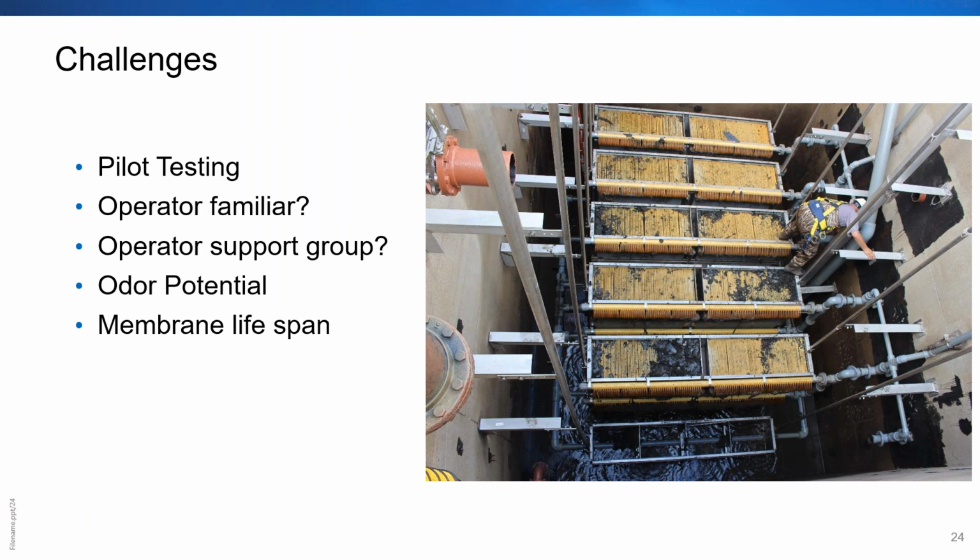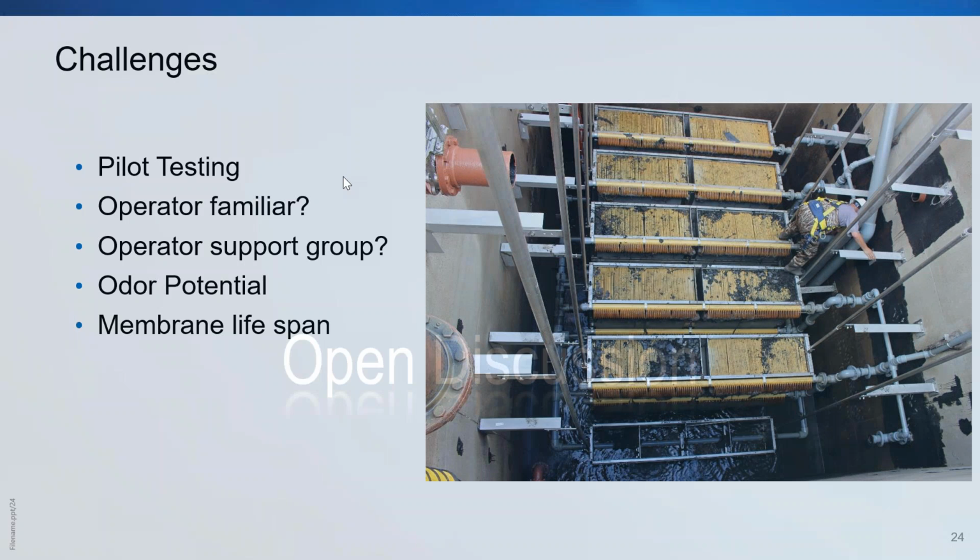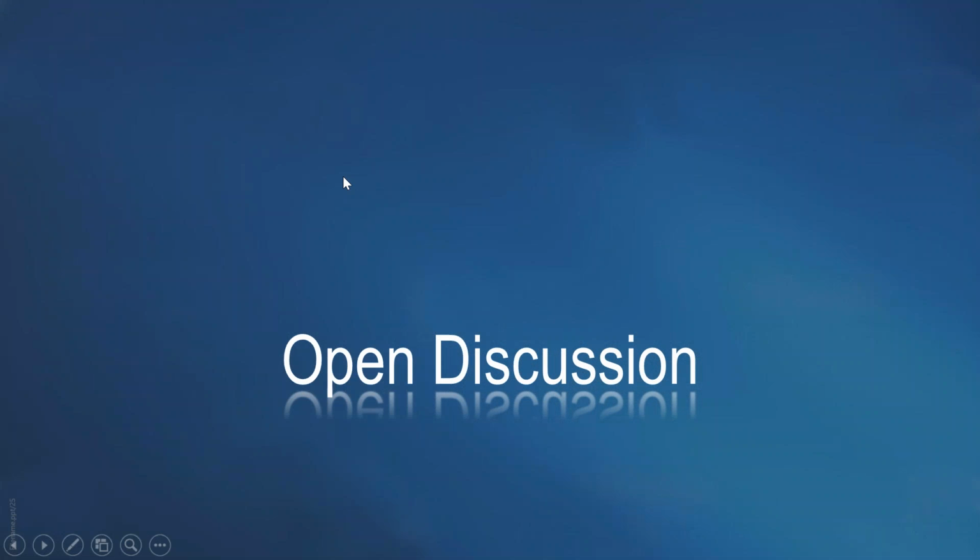And of course, the odor potential. Anytime you have anaerobic treatment, you have potential for odors that you have to capture and treat, and that can become a nuisance depending on where you are. And then the other unknown, because there aren't many full-scale facilities in operation over time, is what this means for membrane lifespan compared to typical MBR situations. So I think with that, I am at my allotted time.